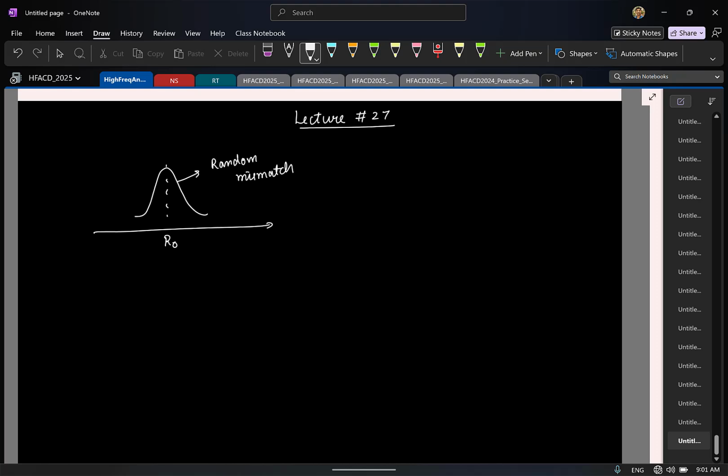Now if you take the mean value of all the resistors from one chip to another chip, those mean values will also show variation, and that can be anywhere between 10 to 20% from this nominal mean, and this is what we refer to as process variation. And in practice, for the process variation happening for MOSFETs, we give some special names.